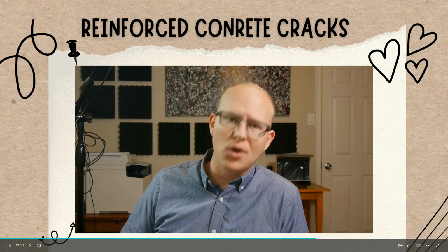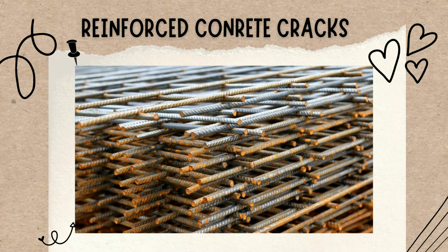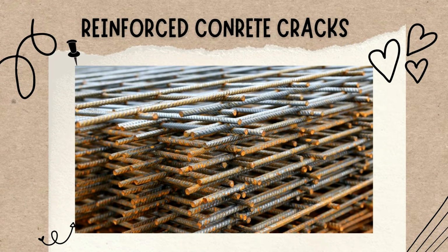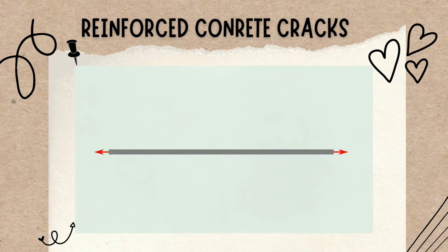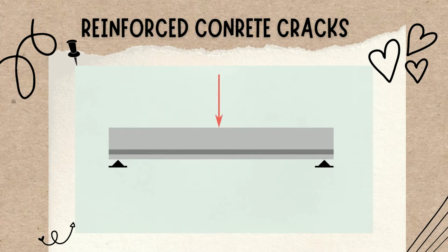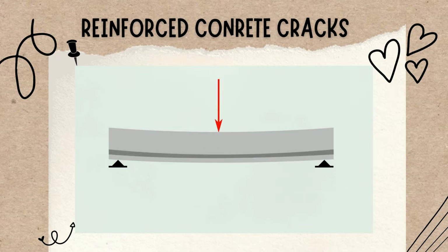In the case of concrete, deflection has another impact: cracks. The reinforcement within concrete is usually made from steel, and steel is much more elastic than concrete. So in order to mobilize the strength of the steel, first it has to stretch out a little bit. But unlike steel, concrete is brittle. It doesn't stretch, it cracks. So that often means that concrete has to crack before the rebar can take up any of the tensile stress of the member.